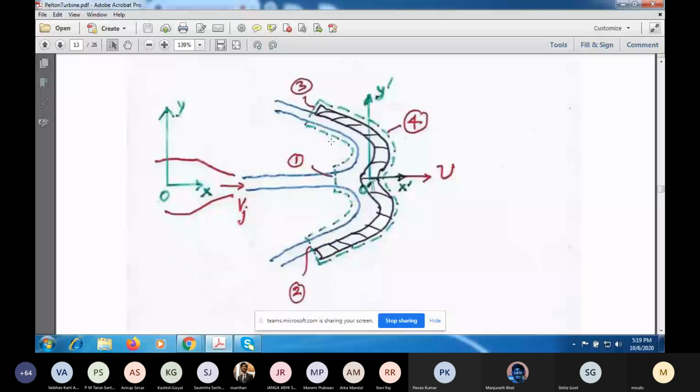So if you consider a fluid particle here at the exit, just outside the exit, there is no net force due to pressure because the pressure distribution is uniform. So the acceleration of the particle will just be equal to the gravitational acceleration, approximately.